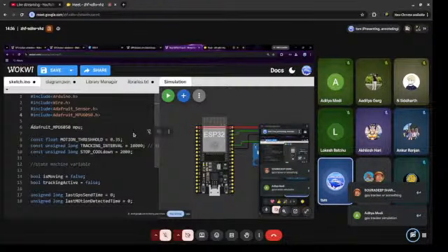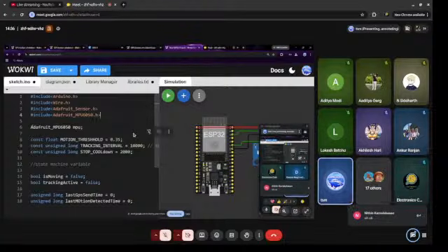And Wire.h enables I2C communication. The ESP32 uses this to talk to the motion sensor, and the Adafruit Sensor library gives a common sensor interface, and MPU6050 contains all functions required to communicate with the MPU6050 accelerometer.